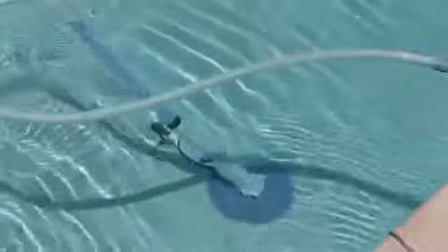So there we go, there's my pool cleaner. And as you'll note, it is comfortably ticking along, and my pool, as long as I clear out the leaves after it's been a little bit windy, is kept perfectly clean by running it at lower RPM and even a really low RPM during the afternoon. And as you can see, the cleaner is still running at a rate of knots, and all I did was buy a really cheap pool cleaner and the connector in the weir, which I'll show you. You can adjust the spring to allow it to work at different pressures, and that allows it to work quite comfortably at a lower pump pressure.